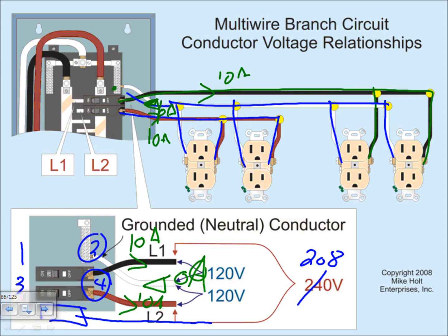Who cares? Then the multi-wire branch circuit is not carrying as much current. So if you put a clamp on the neutral, you will get 0. There are some harmonics that could be created, not in residential, but when you go to three-phase harmonics, if the equipment is electronic, it could screw up the value for you. But if your system is all 100% resistive load or motor load, no harmonics, nothing electronic in it, you'll get a 0. And who cares, guys? Beautiful. If you get a 0, then there are no losses in voltage, no losses in the power, nothing.